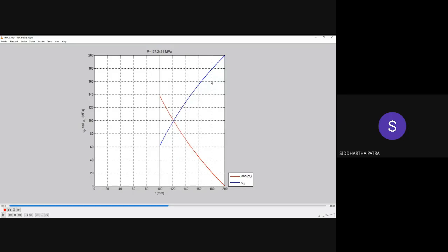Okay, and now I am reducing the pressure, so now I'll be developing residual stress. But you see, in this particular example, I have gone up to P double prime, that is the maximum load bearing capacity, and then started unloading. The point being that my entire cross section has gone through plastic deformation, and I don't have separate elastic and plastic zones where the unloading takes place with a different set of residual stresses. So I only have the plastic zone, and I am unloading from that maximum pressure P double prime. So my unloading stresses would be calculated based on P double prime.